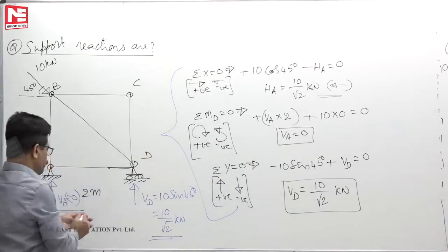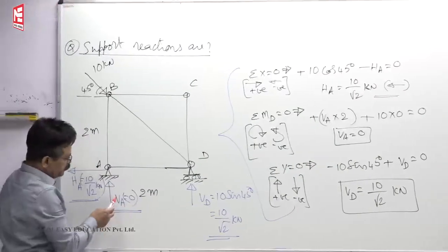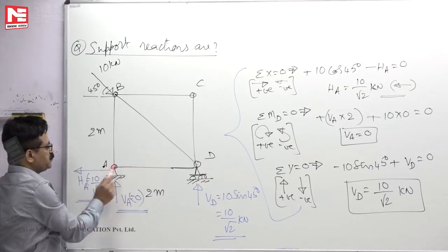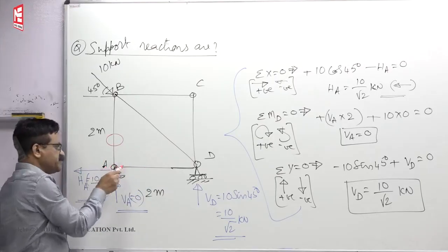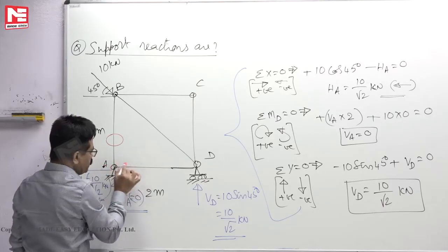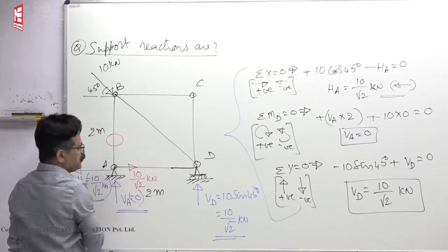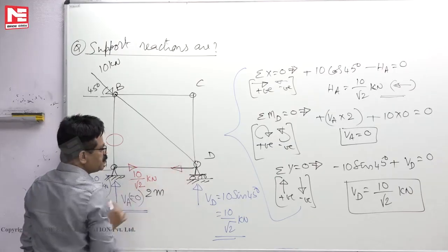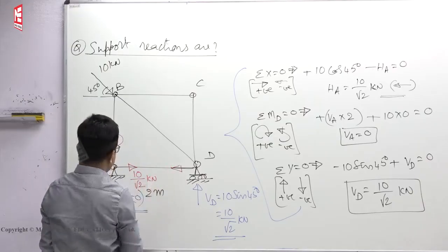Now, member forces we want to see. Assume that I want to start from here. VA is 0. Once the geometry is cut, throw it out. Now, how many members are there? 1, 2, 3. 2 are in line, the third has to be 0. Then what is the force in the member AD? 10 by root 2, left side, arrow mark. On the pin now it should act right side, 10 by root 2. Now you see, if the arrow mark is away from the joint, the far end also the arrow must be away from the joint. Over. So 10 by root 2, in one place you write 10 by root 2, enough.